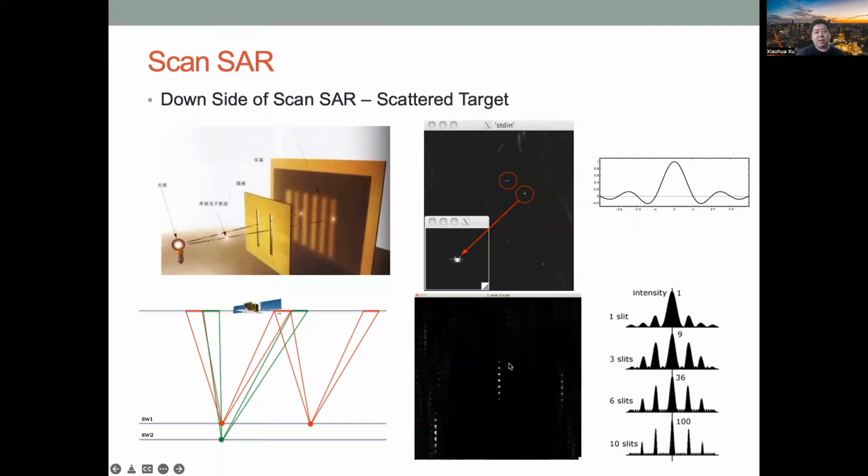The problem from the last slide is actually when you're doing cross-correlation, or in other words, trying to match these two radar images together, these peaks might be misaligned to their secondary peaks. So that's why that part of the image is misaligned and has this decorrelation issue. However, luckily, these side dots or side lobes are not too close to the center, so we can do some tuning to make sure that the correlation happens only on the major peak to avoid such situations.